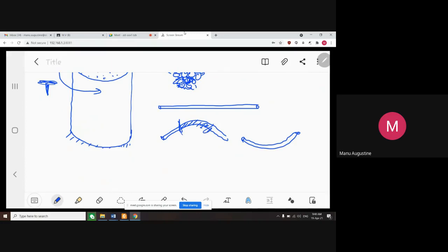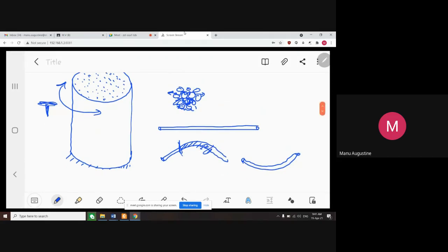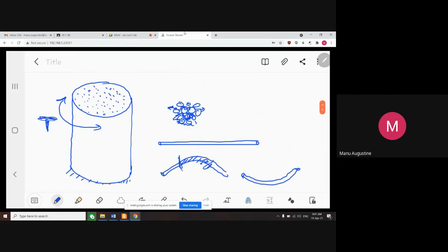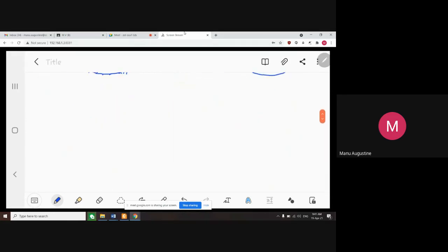Now, where is this heat coming from? This heat is coming from the internal friction of the atoms and molecules. So this is the concept of hysteretic damping. The energy of oscillations in the case of hysteretic damping is released as heat, or lost to the environment in the form of heat, because of intermolecular or interatomic friction. So this is the basic phenomenon of what we call the hysteretic or structural damping.